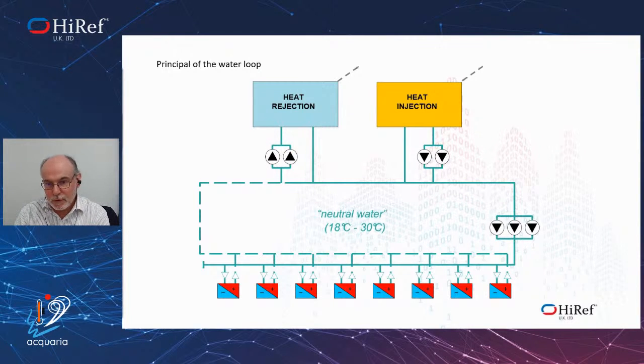And so you end up with a number of heat pumps working with heating or cooling in an office space and retail. Because of diversity around the building, that can help, because in certain areas some parts are cooling, where in another part of the building it's heating.